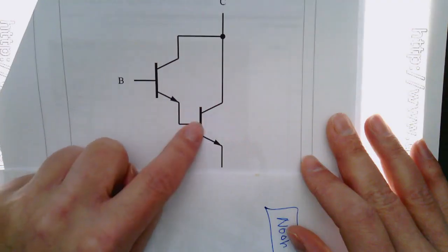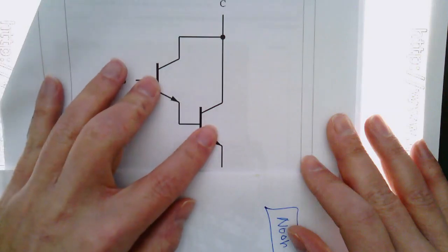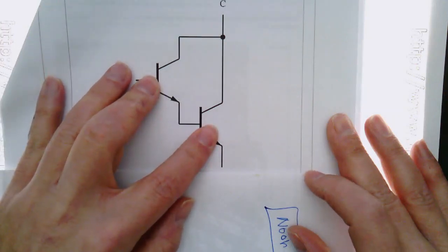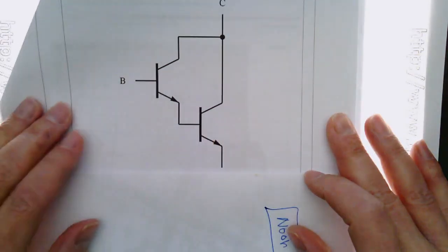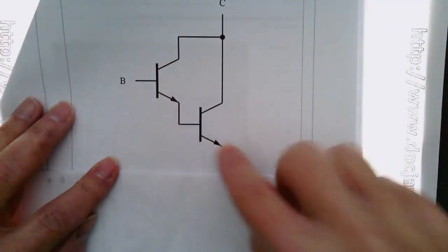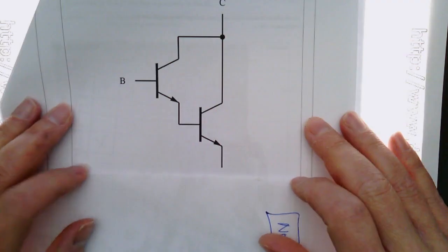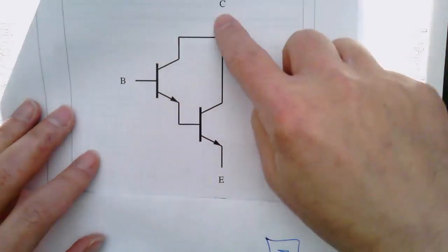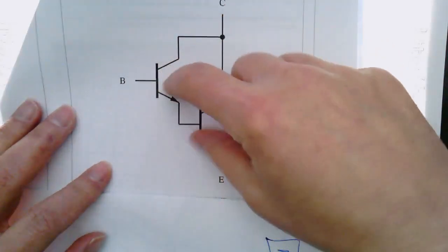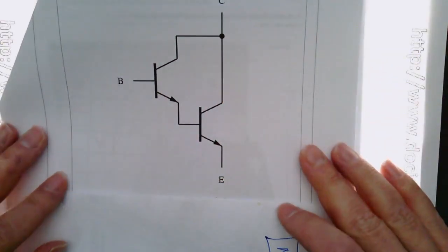And by cascading the two transistors together, you can obtain a higher current than by using a single bipolar junction transistor. And together, it's called a Darlington transistor. And that gives you a higher current by using two bipolar junction transistors. And you can actually get these in an array in a single chip, and it will drive stepper motors from something relatively low current like an Arduino. So the answer to that, and there's your collector and there's your emitter, these two transistors can be made to look as though they're one transistor. Even though the switching speed suffers a little bit, you get a lot more current.